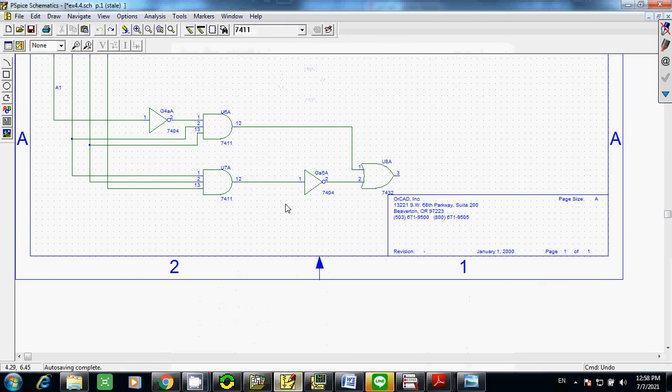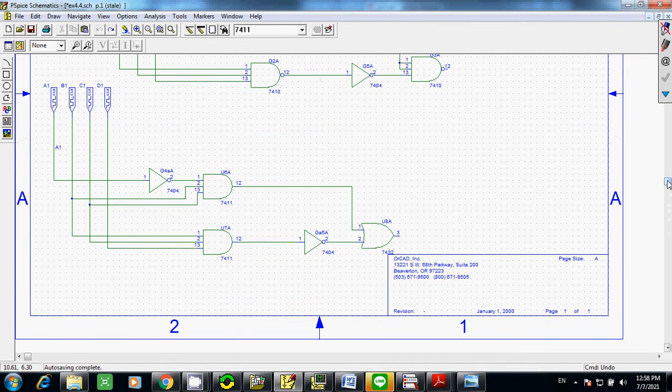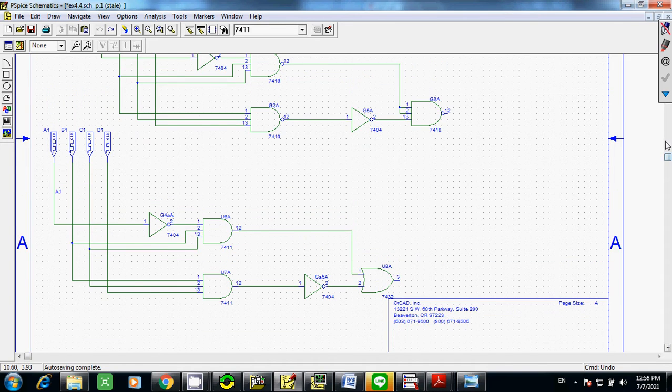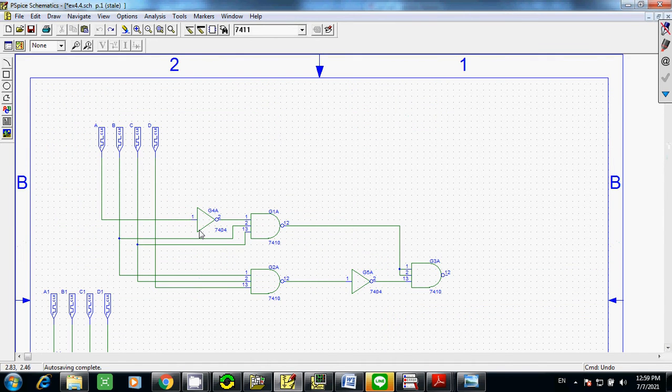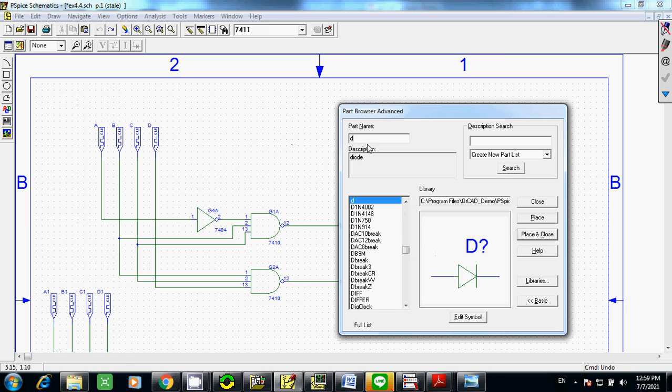Let's go back to your circuit here. And because I just want to save time, I will redraw the circuit. For a digital clock, you simply get new part, Control G and type DIG, and you can see this one is the digital clock.